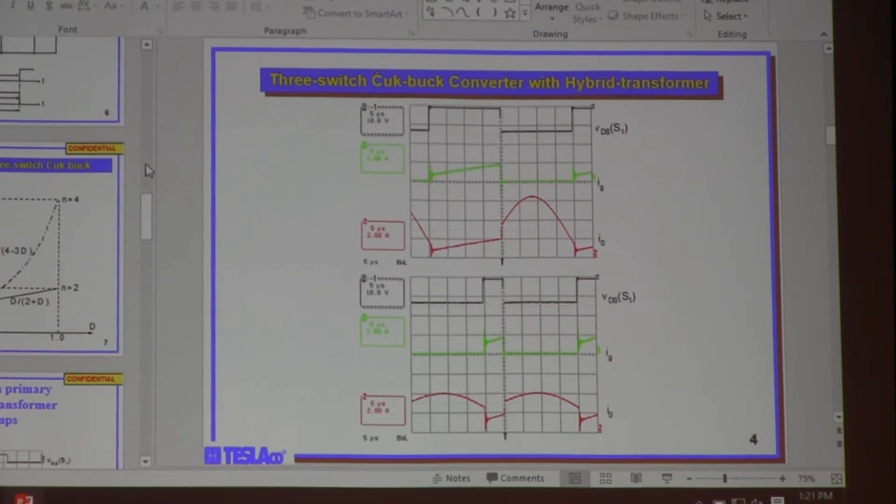And what it means is that at the 50% duty ratio and lower, it doesn't matter whether you use a 5 to 1 or 10 to 1 step down, who cares? You're not getting any step down. Whereas here, in those converters that are using 2, it's here, and in fact, in the other one, you have more and more waveforms. The more turns, the more it starts. Well, basically, step down is 1 over n times d. So you get a full step down. In a tapped inductor, you get nothing, okay? Or very little, let's say 10% or so.